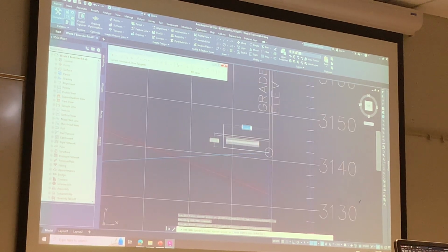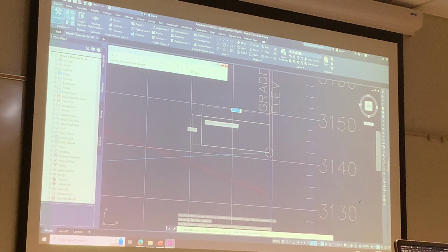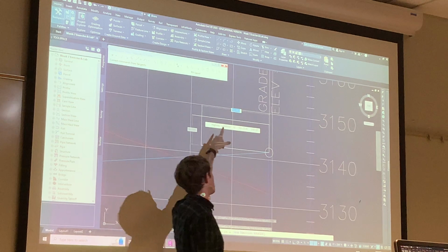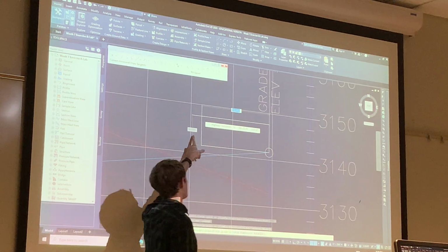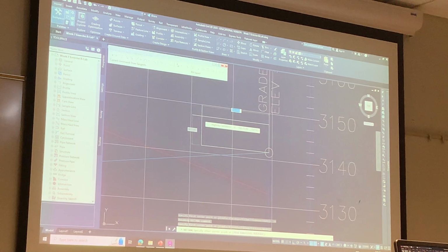So I'm drawing this rectangle. Now you can either type in, you see that it's already got the dimensions showing, right? I'm showing 166 and 60 right here. I could type in 100 there, and then comma or tab into the next one. If you put those numbers in, you're going to want to put negative in for the 100 because you're going to want to move to the left.